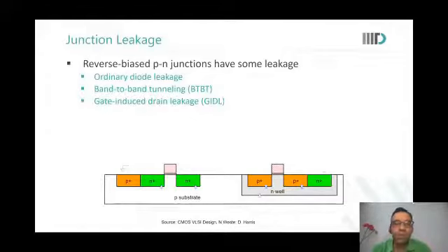Yeah, that is what we showed. In the stack effect, the leakage changes, so the current through the devices is changing. So now the current is not uniform, like for modeling. But KCL will still be followed, no, Madhur? Yes, sir. It will be followed. So whichever is the most resistive device, whichever can sink the lowest current, that will define the total current in the system.